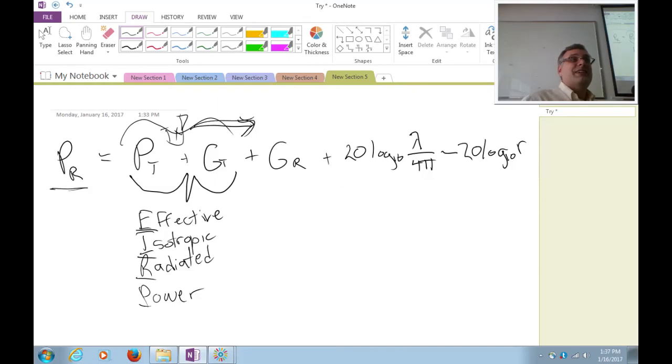So the interesting thing is, when the radio station, and I'm not accusing WREK of doing this, everyone does this, they'll say, okay, I'm transmitting at 10 kilowatts of power, but I've got 10 dBi at transmitting. So my EIRP is really 100 kilowatts, right? And there are even some radio stations that transmit a lot more than WREK, the Georgia Tech radio station. They maybe transmit 50 kilowatts, and they got a 13 dBi antenna, which means they really got a megawatt